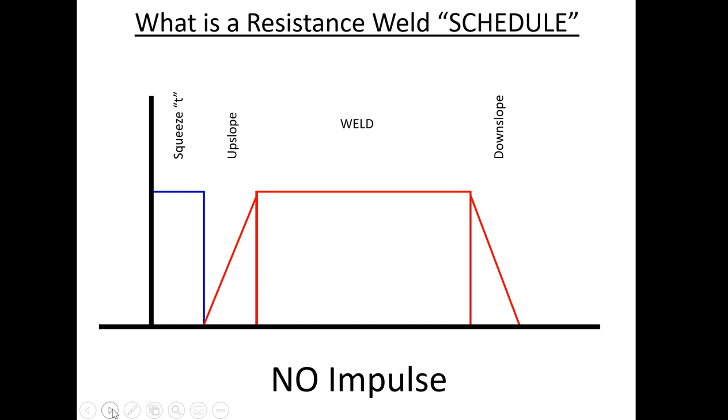if you stretch out your downslope, you're starting to anneal your joint a little bit. So if I take my time cooling off, remember, the slower I cool, if you watch the metallurgical side, you know that the longer it takes to cool, the softer the composition of the material will be. Fast cool embrittles, right? But if you don't have the carbon content, if your material, again, is just a plain carbon at 1010, 1008, you could go ahead and quench that as fast as you want. You could hit it with a hose if you want. It's not going to make any difference because it doesn't have the potential. It doesn't have the metallurgy to be hardened. And then, of course, our hold time until cool.